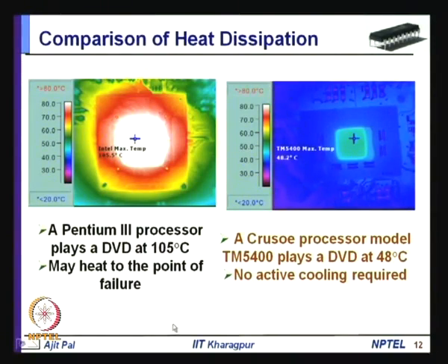So, this demonstrates the efficacy of the approach proposed by Transmeta. Essentially, it is a trade off between hardware and software. The hardware which is implemented in superscalar architecture to perform instruction decoding, instruction dispatching, then reordering, are being performed by a piece of software in the Transmeta processor by using VLIW architecture.